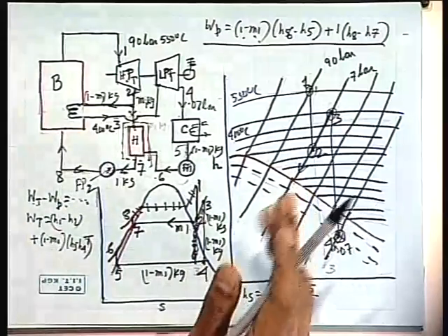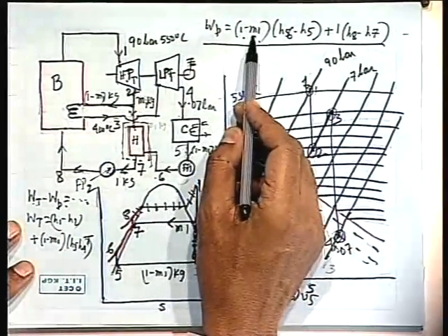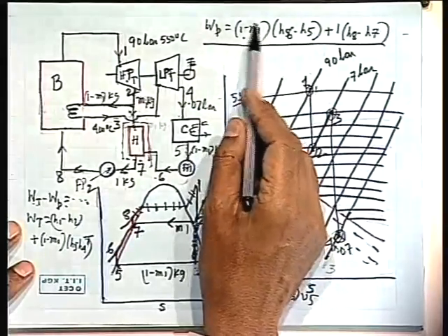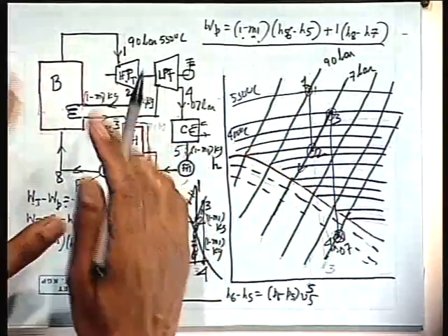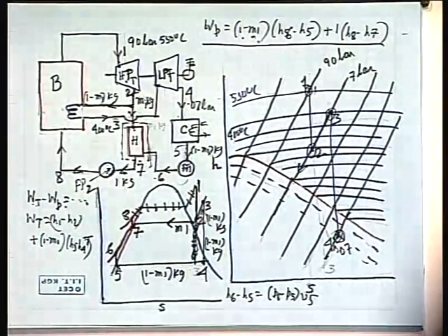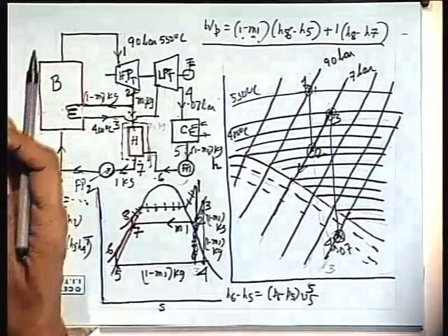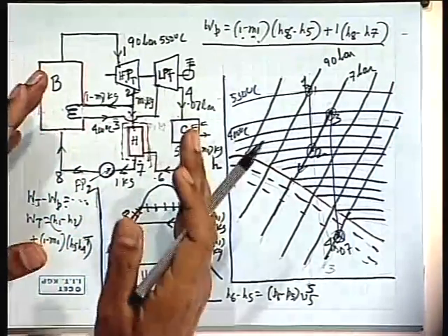For examination I may deduct a few marks, but the actual answer will be with the total mass flow M1. This M1 is per 1 kg. So the pump work is for 1 kg of flow to the HP turbine. Already I have found the steam flow rate through the HP turbine, multiply that. That means the total pump work. Like that, total net work is given.